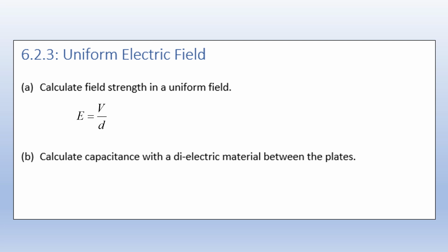What we're going to start to look at now is, we already had a look at capacitance with a vacuum in between the plates, though we weren't aware at the time that that's what we were doing. But if we put another material between the plates, that's called a dielectric, we can affect the capacitance. So we can actually calculate the capacitance if we know a few properties. The surface area of the plates affects the capacitance. The plate separation changes the capacitance too.